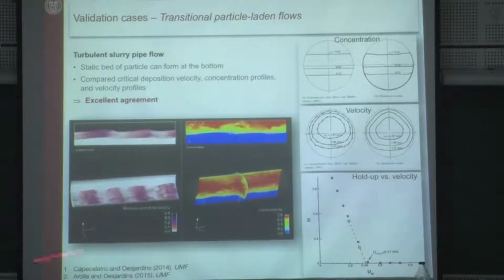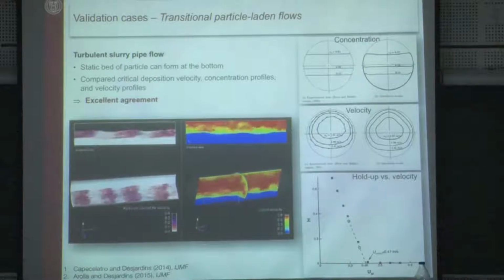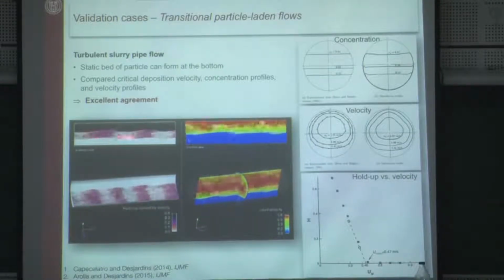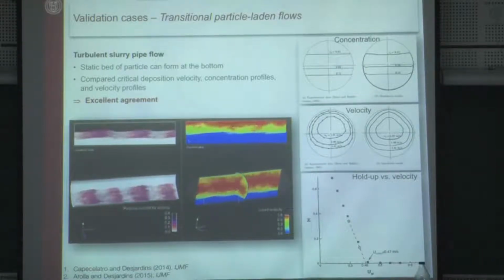If we were to approximate what's going on in here, we're essentially solving Darcy's equation. This is now a porous flow model, except we don't have to manually do anything. This is already contained in our equations. At the surface, we see that we're naturally forming dune-type structures, which are known to form naturally in sediment transport. And then you have a transport layer at the surface, particles bouncing around, et cetera. The big question for us is, can we predict the cross-sectional area of the pipe that is blocked by the presence of a static bed as a function of the velocity at which the water is flowing?